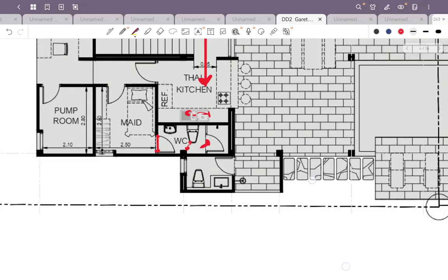And then the other thing, normally we will try to have about a 10 centimeter door offset from the wall here, 10 cm. Why? Because we can open the door 90 degrees and the doorknob does not hit the wall, and then you can install the door stopper here.